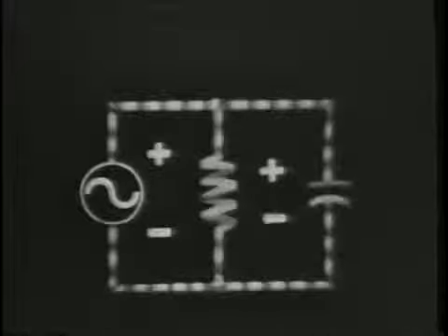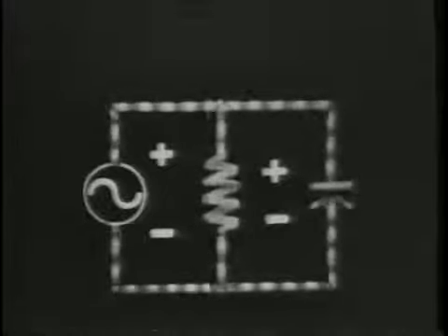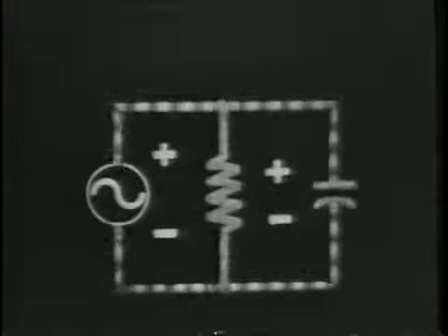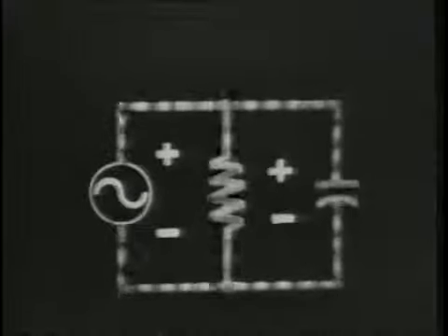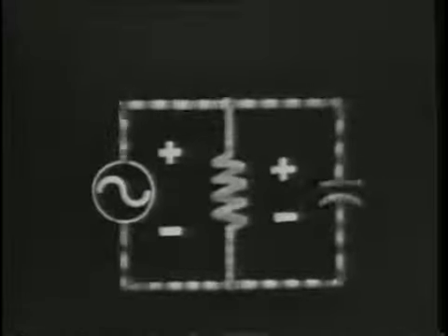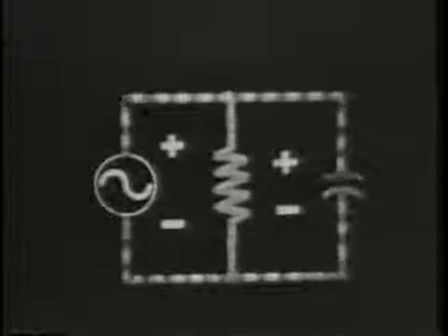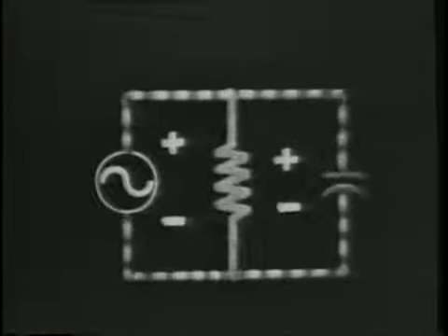On the next alternation, current flows through the resistor in the opposite direction, and power again is dissipated. But the capacitor simply returns the energy stored, and again no power is dissipated in the capacitive branch. Therefore, only the resistor dissipates power, but both components draw current.